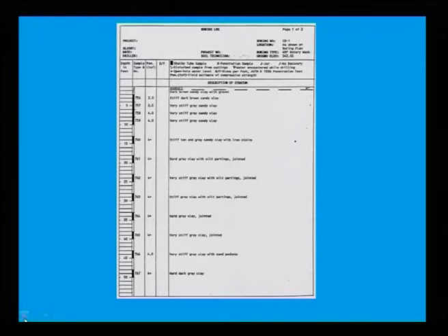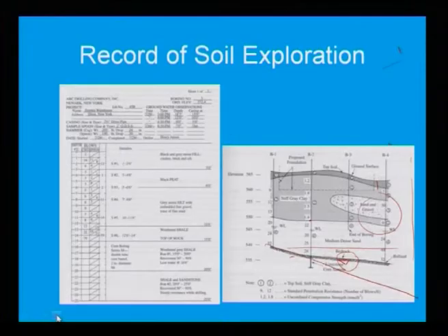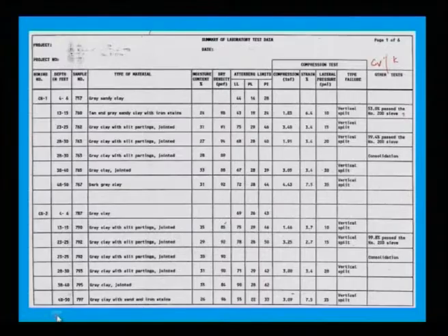This is your first report, first page: bore log data, simple depth, type, penetration and your classification. On page 1, if possible, in a second attachment or second profile, give penetration blows every 15 centimeter depth. Then you can show how the soil profile is varying, how the water table is varying, and what your bedrock is. You can provide a small diagram. This is your page number 2.